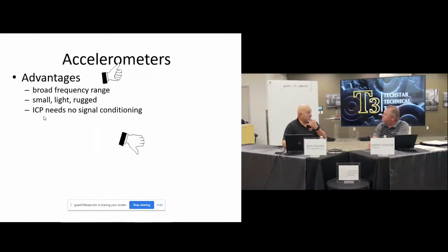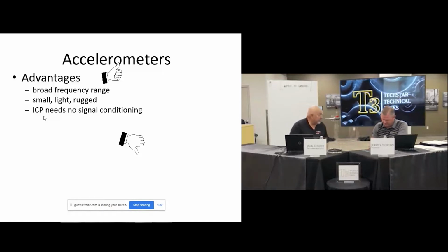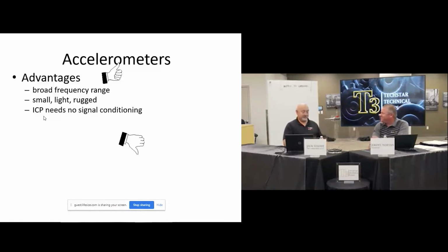One of the other things I want to talk about on accelerometers: if you do have one go bad, throw it away. Don't mess with it. There's no way of repairing it. I've walked in places where they have 5-gallon buckets of broken accelerometers, and I ask, "What are y'all going to do with those?" And they say, "We haven't decided." Well, to be fair, I don't know of anyone that repairs accelerometers under warranty. Typically, you get a new one sent to you. Now there are companies with lifetime warranties on some of their accelerometers. Back in the old days, you had your bucket full.